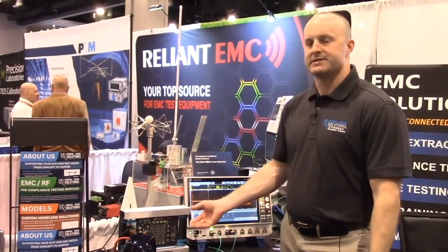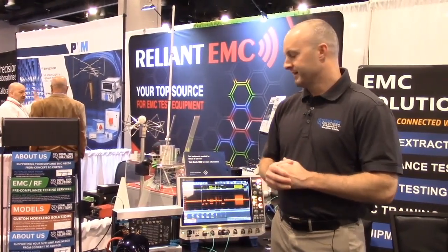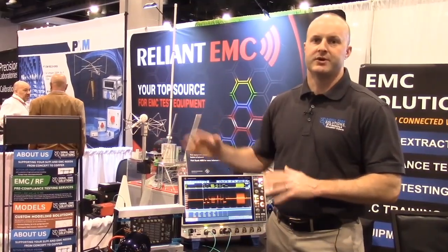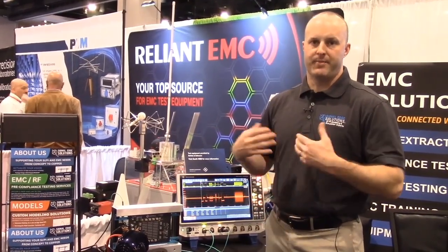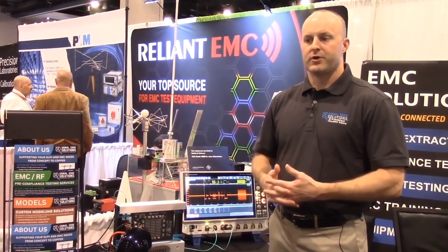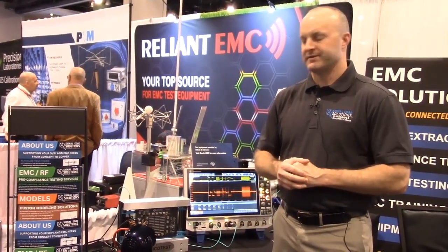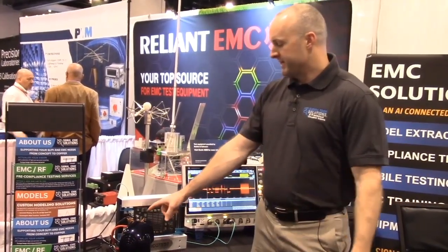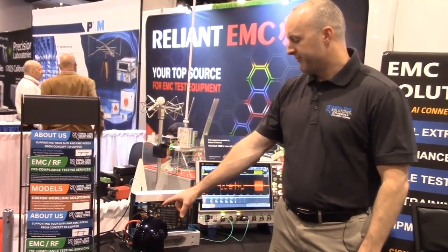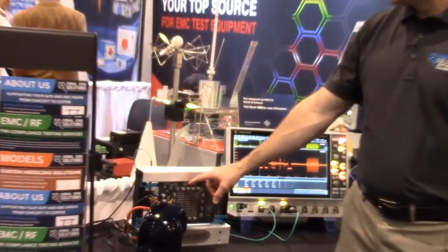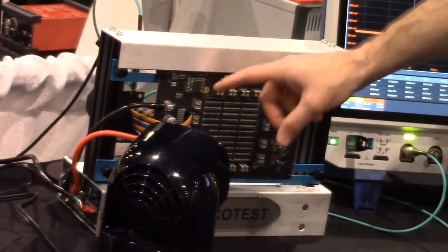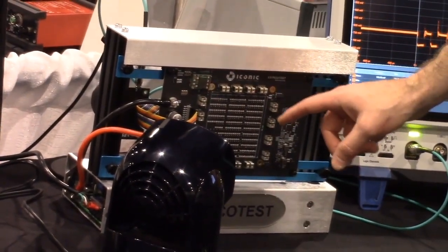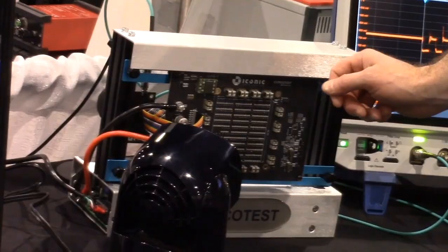What the transient step load solutions from PicoTest do is they allow us to decouple that software schedule, do that large signal emulation, and validate our power supply and our power system to ensure it's going to work before you plug in and test that expensive ASIC. In this case, we're taking 48 volts to 12 volts with these LSE converters. These LSE converters are piping 12 volts down to these buck converters, which are surrounding the outside of our step load. And these buck converters are stepping down that 12 to 0.8 volts.